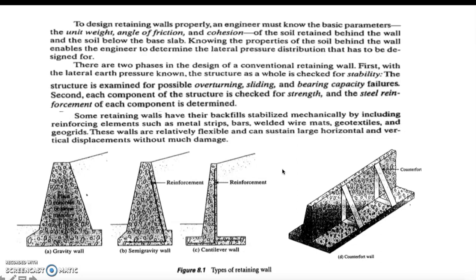In dams, in fluid mechanics, you just cover checking for overturning and sliding. However, in foundation engineering, you're going to have an additional check. Aside from overturning and sliding, you're going to check for bearing capacity failures.